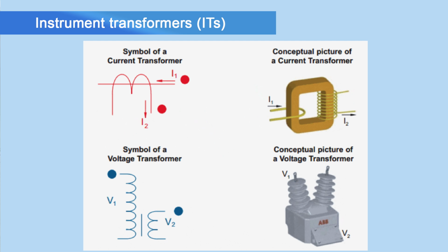For this purpose we are going to use the instrument transformers, and in addition to that they can act as isolation between the instruments and the high voltage circuit.